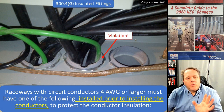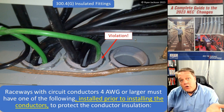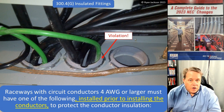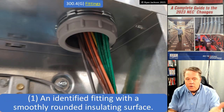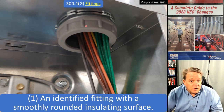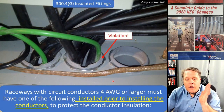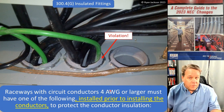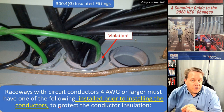It says raceways with circuit conductors 4 gauge or larger must have one of the following installed prior to installing the conductors in order to protect the conductor insulation. All right, so let's just look really quick at one of the items. The most obvious one would be an identified fitting with a smoothly insulated surface. So one of these plastic bushings. All right, so let's go back and reread it with this in mind. If I have circuit conductors 4 gauge or larger, then you have to have a plastic bushing or something else installed prior to installing the conductors in order to protect their insulation.